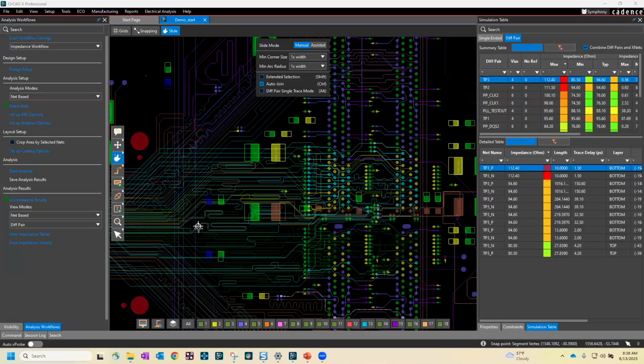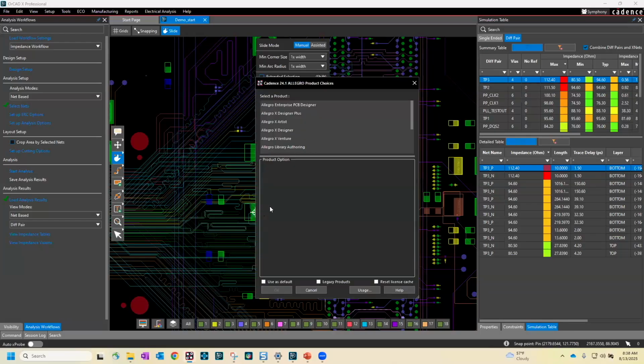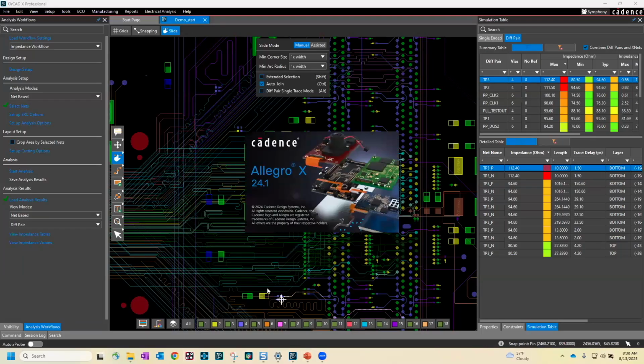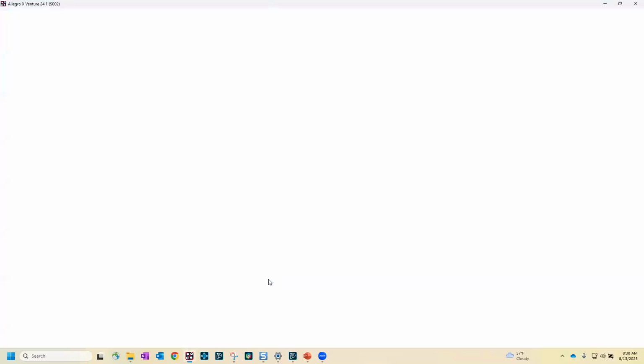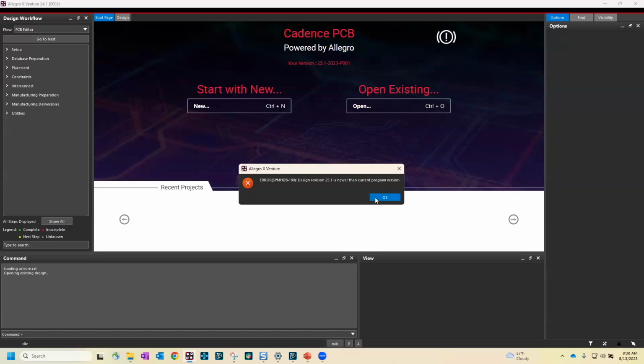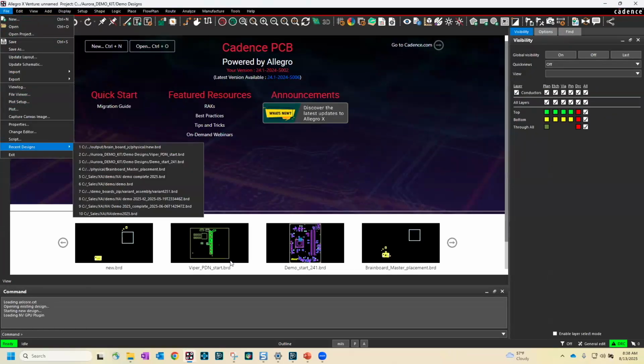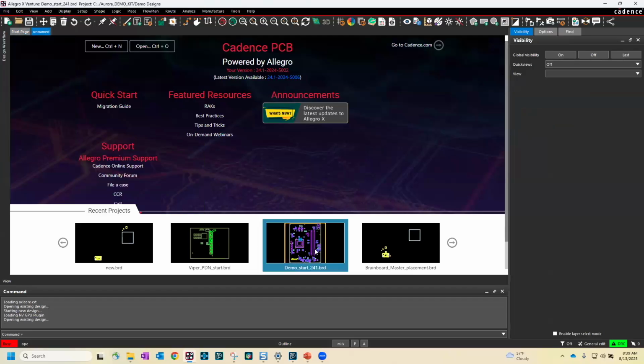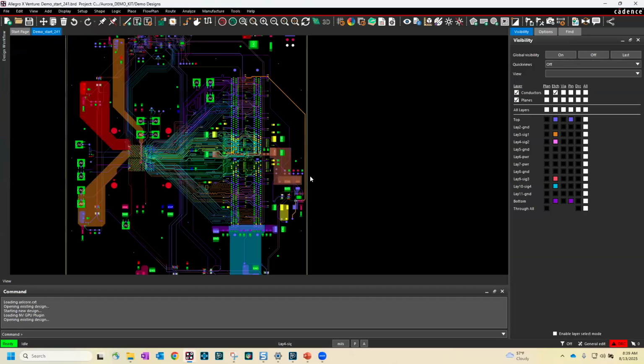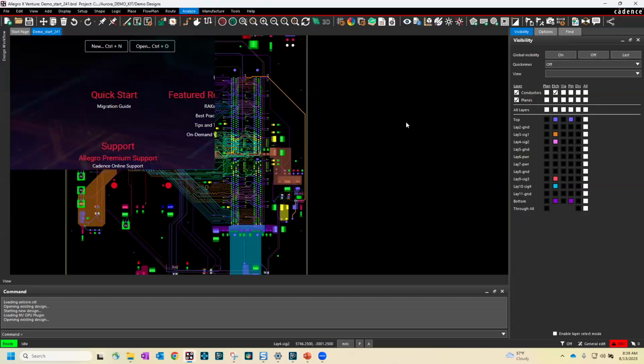Okay, we had some questions on how to generate the power tree while you're doing that. You can generate them from Sigrity power tree if you have that installed and available. Otherwise, if you're using a tool like System Capture, you can generate a power tree in there, and that will output the power tree setup file, which you can reference within that IR drop workflow.